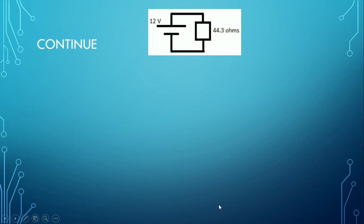So now we're going to solve for the total current. Now that we have our simple circuit here, we only have voltage, resistance, and then we have current, which we have to solve for. So since we know V equals IR, the total voltage equals the current times the equivalent resistance, which is 44.3 in this case. So if we move the R and divide both sides by R, we will get the current. So we basically substitute 12 volts as the total voltage, 44.3 as the equivalent resistance of all of the resistors together, and we get a current of 0.27 amps.